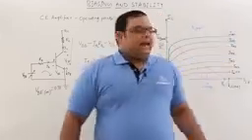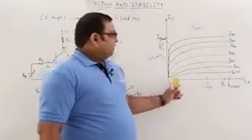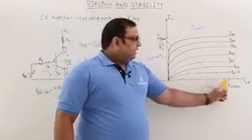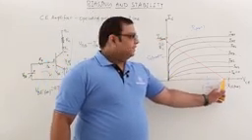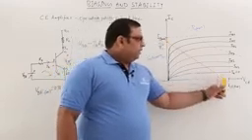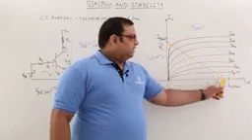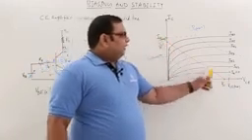So here consider this graph. This is the Vcc axis. So when Ic is 0, correspondingly this output Vce is nothing but Vcc. So when you join these 2 points, we will get the load line. We call it the DC load line of the transistor, and the slope of this load line will be equal to